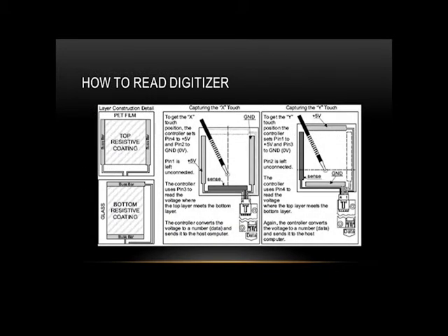A brief overview of the technologies involved. We're using a resistive touchscreen digitizer. To use the digitizer, you have to ground one side of the sensing bars and drive the side that's opposite this bar. This creates a potential difference across the resistive layer.